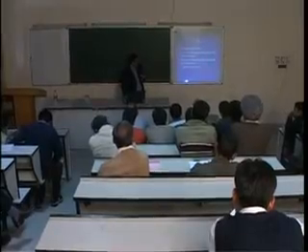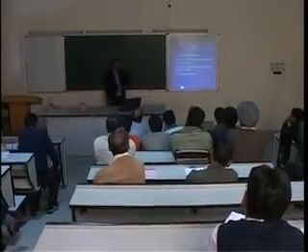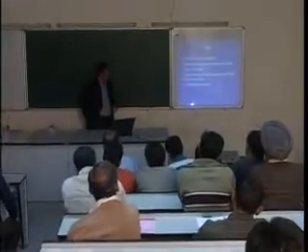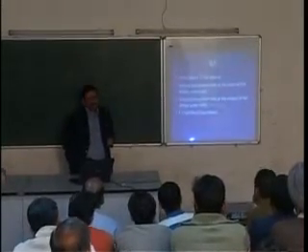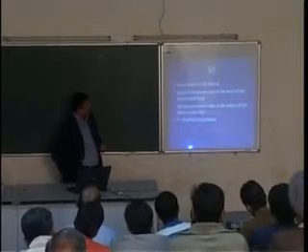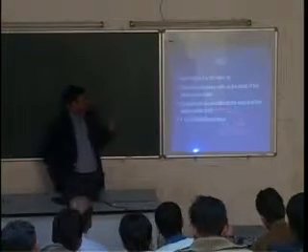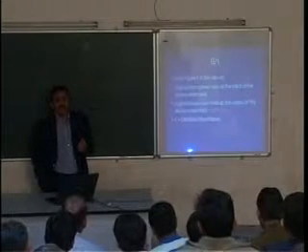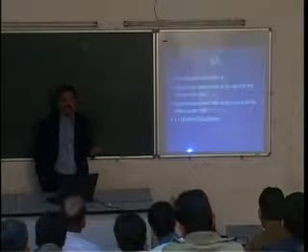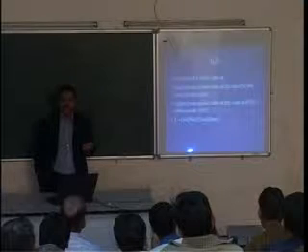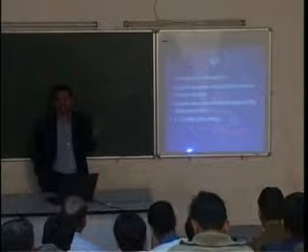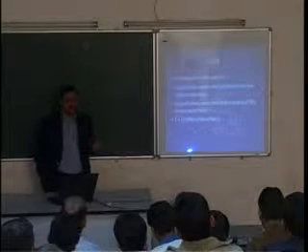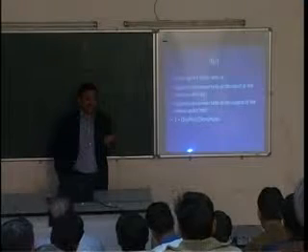Now the last is our G by T measurement. I am sure you must know that this is called the figure of merit of any antenna system, and we generally measure the ratio between the gain and the noise temperature. The gain, everybody knows how to measure, how you measure the radiation properties, but how do you measure the noise temperature? That is the only key in this. How do you measure it? Because you know the noise temperature of your device or low noise amplifier.